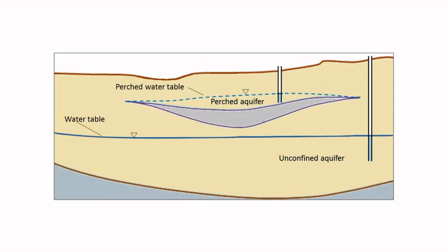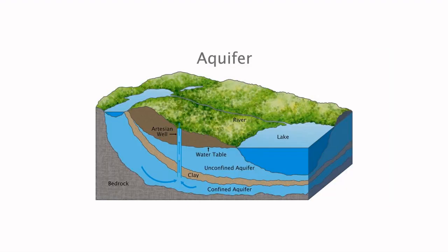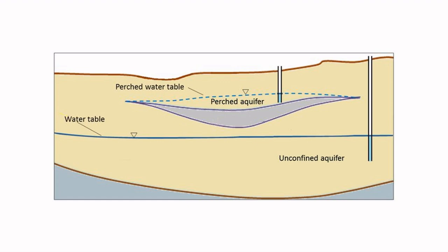The water table is actually a theoretical surface which is approximated by the elevation of the water surfaces in wells which penetrate only a short distance into the saturated zone. A more exact definition states that the water table is the surface in unconfined material along which the hydrostatic pressure is equal to the atmospheric pressure.